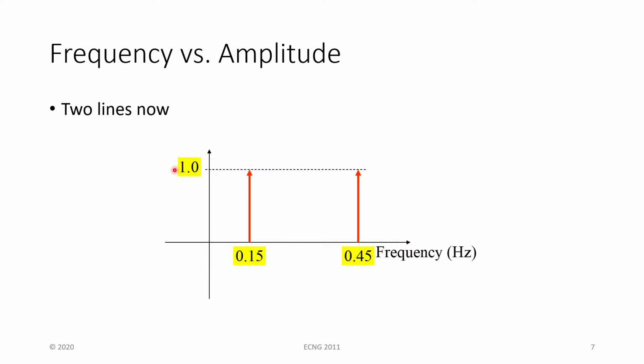So when we do the amplitude versus frequency graph here, we just draw the individual frequency components of each one of these signals. If for some instance, let's say the cos 3 omega t graph had a different amplitude, let's say it was like 0.8 or something, this arrow will just drop down to represent this change in amplitude for 0.8.